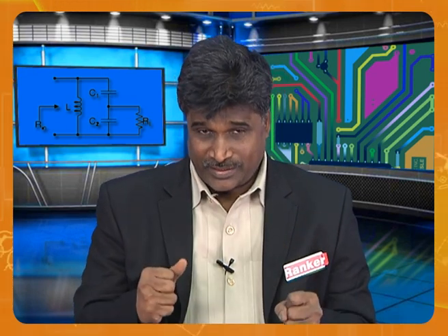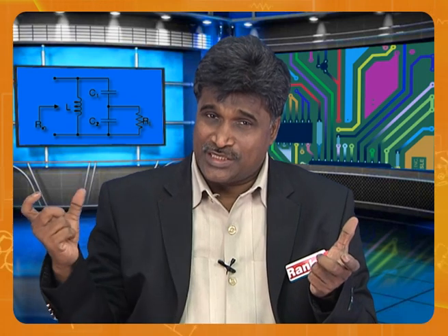So maximum power transfer theorem is a very important thing. Suppose having done all these Thevenin's equivalents, if the load is not matching, the whole purpose gets wasted. Therefore, remember, maximum power transfer is possible only when the equivalent impedance of the circuit is equal to the load. That's called matching. Maximum power is transferred. So this is the second case. The third case is also there, general.